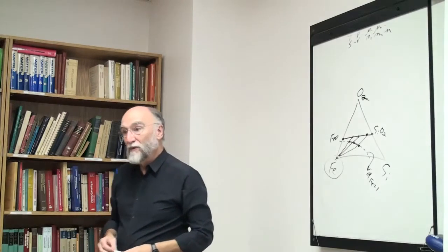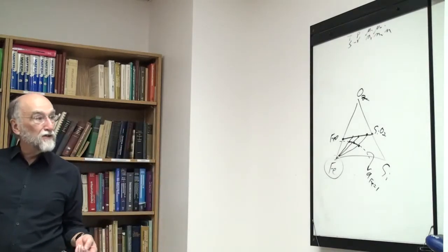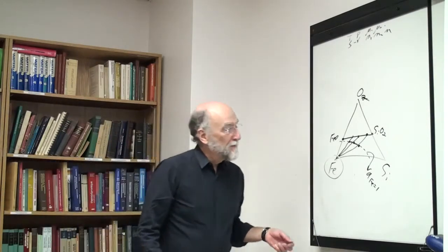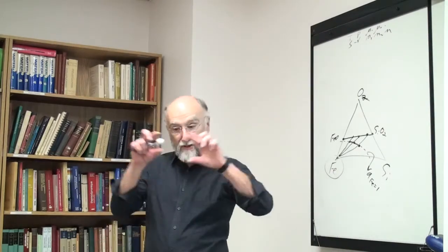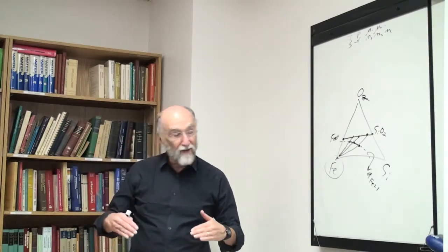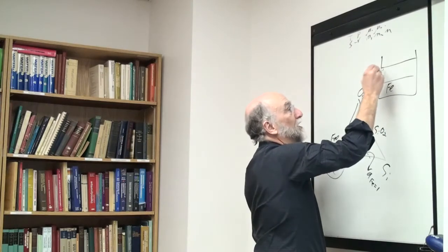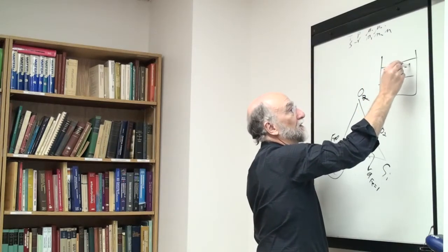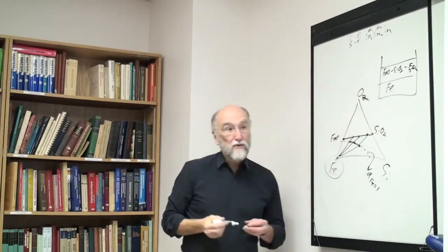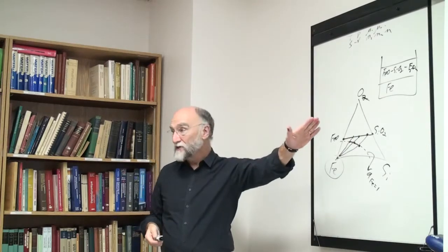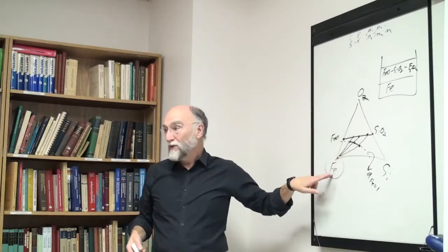Okay. The trouble with that, of course, is that that's fine, and in this particular case it's pretty close to the truth. Because the iron phase, if you actually set this thing up, if you had your high temperature slag, your oxide phase is in equilibrium with the metal phase, the thing is now going to be at equilibrium. So you're going to have down here, you're going to have iron, and up here you're going to have your FeO, silica, plus iron, Fe2O3, whatever phase, your slag phase. If the iron is pure iron at equilibrium, then that's the same thing. It's exactly analogous to fixing PO2, except for fixing this other component's activity.